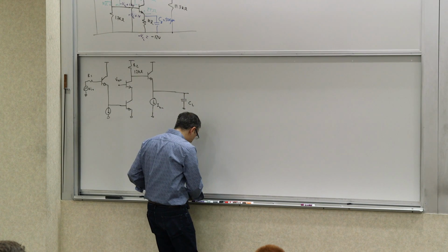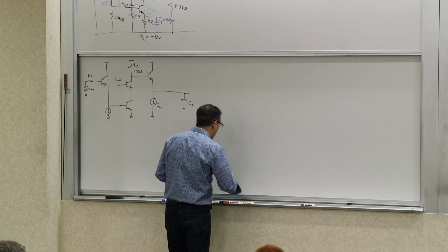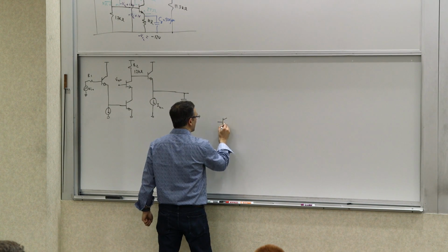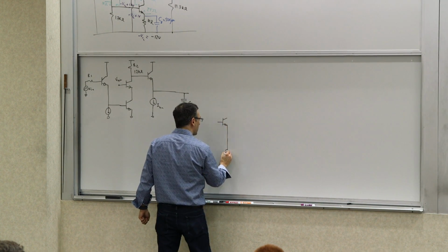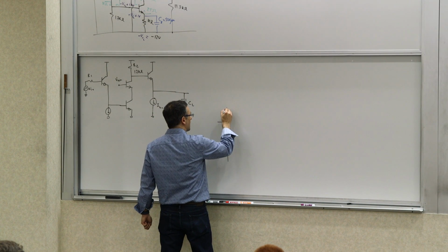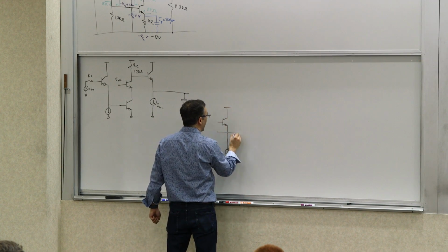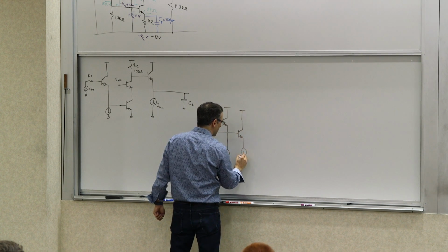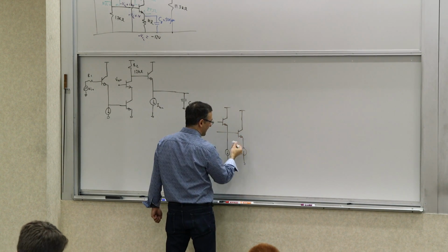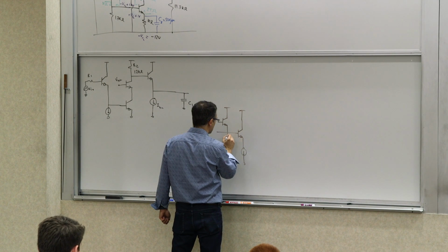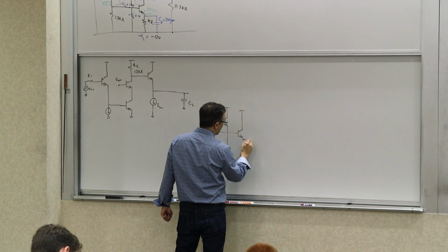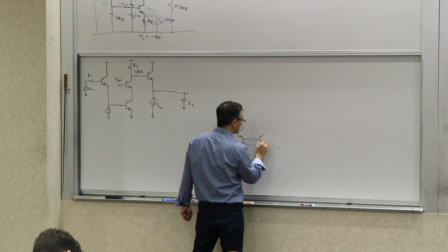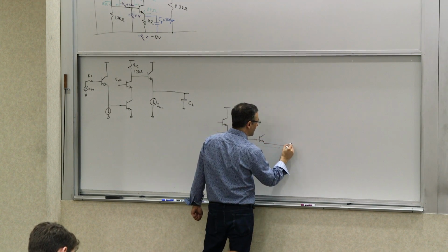So the way we implement it as a differential circuit, if we take this circuit and design it as an integrated one, we could have 2 followers. Now we can have current sources, right? Current sources are not a problem. So you can actually have a differential input. You can have 2 current sources. Now, current sources we know how to make. We can turn them into a real current source, or not. And then you can bring this input to a differential pair. So you form a differential pair.